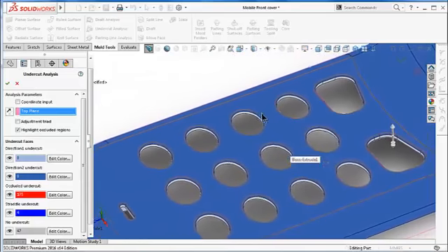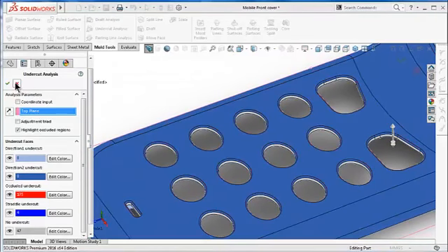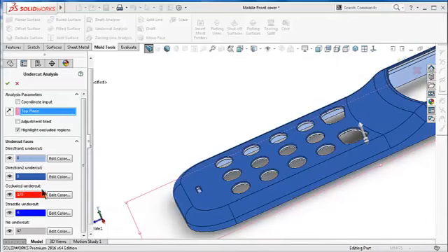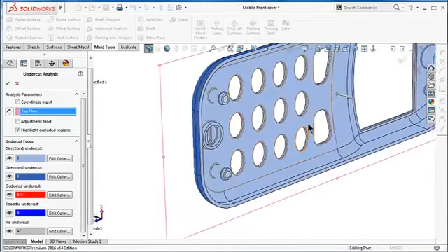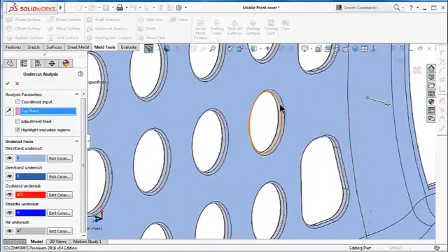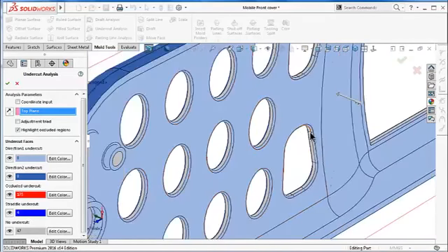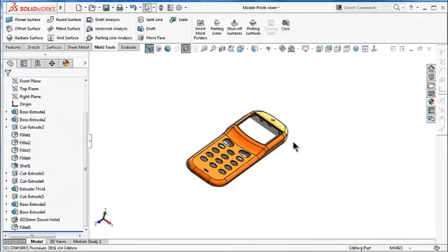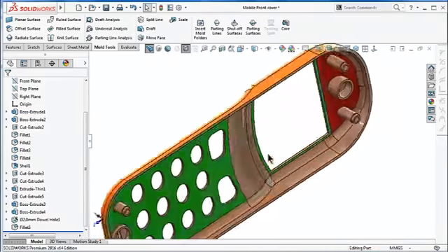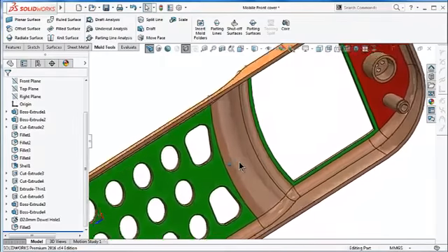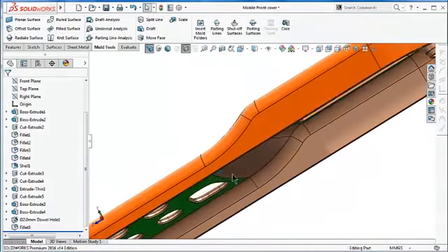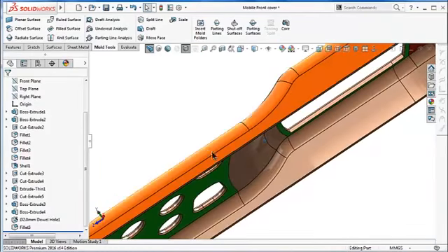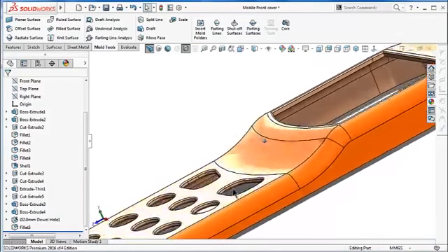And to make it clear, we can try to make another example. The occluded undercut in this case is because of the fillet over there, and it might not be that big an issue. It can be easily extracted from the mold. So as we said, the undercut faces are so tiny, and by imagining the injection direction, they will not represent any issue.